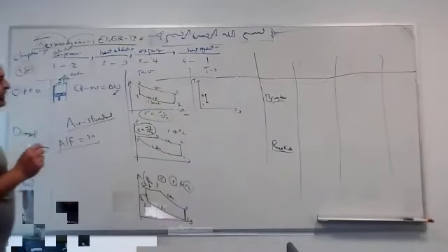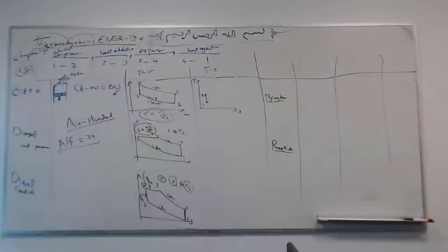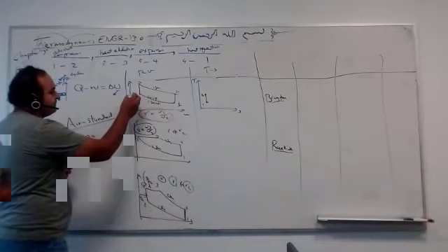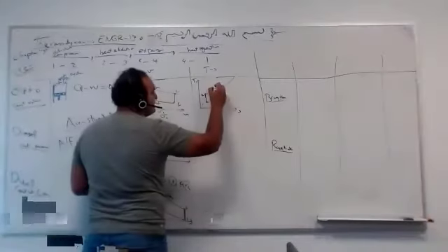So how about 2 to 3, heat addition? For Otto, heat addition is at constant what? Temperature? No, it's constant volume. Constant pressure, constant volume. These are the 3 cycles we are talking about here, in chapter 9.4, 5, and 6: Otto cycle, diesel cycle, and Dual cycle. Otto is constant volume here. So this is vertical, which is here like this. This is always correct, guys.